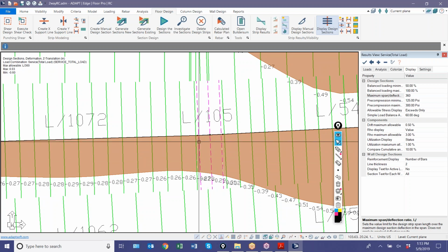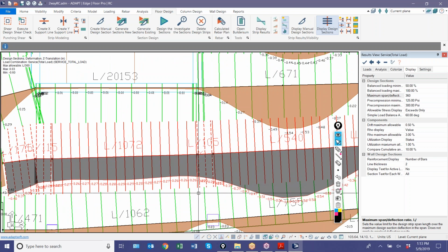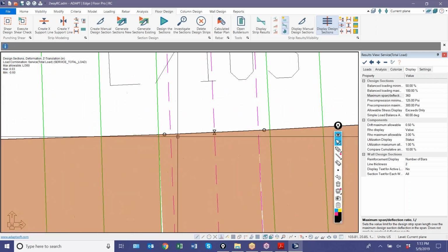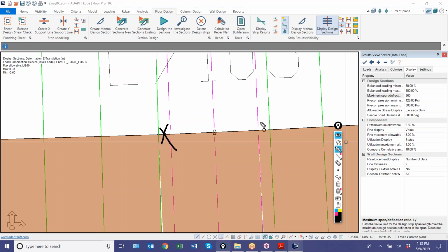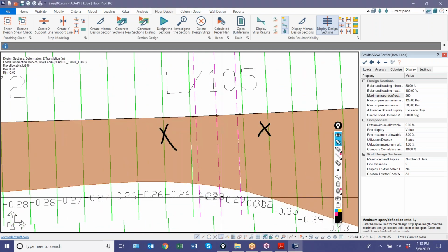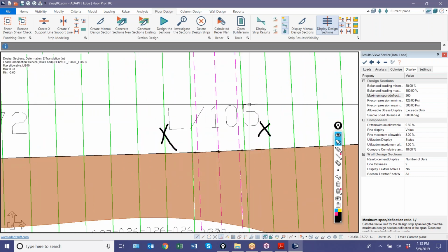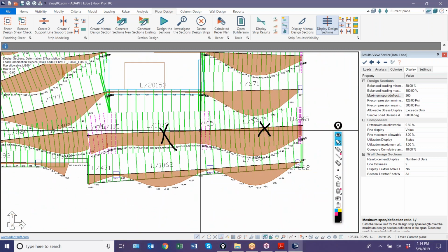Okay, so this is a unique case here. This is a middle strip, so the program has actually created a small span along that middle strip. The span is defined by that point and that point. So the maximum deflection between those 2 points is around 0.28 inches downward. So it's taking that distance over 0.28 and giving you this. So this is more of a false alarm, if anything, because of how the program generated the middle strips and the points along the middle strip.